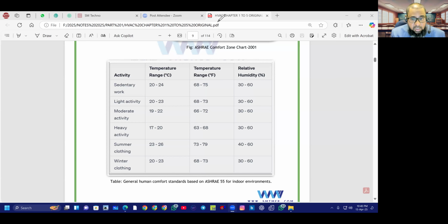So that's the reason to focus on the concept. Once you know the concept, once you know how to design, then for what to design, you need to learn from the application handbook, meaning what the requirements are, and you will be able to design. For example, if you know how to deal with the load calculation for an office, and in that we are considering 76-degree Fahrenheit standard temperature. Same if you want to go for a data center, the temperature will change, say 15 degrees centigrade. So these values will change, but the concept is going to be the same.